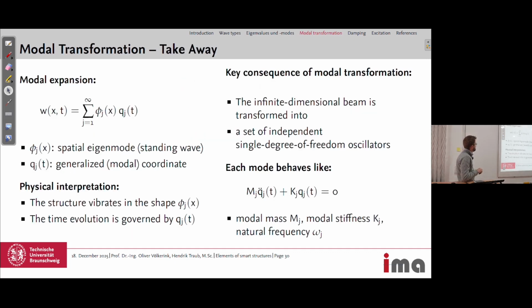So the takeaway is, if we assume this general solution with the separation ansatz, so the spatial eigenmode with its standing waves, and the generalized modal coordinate, which describes the change in time, then the structure vibrates in this shape, and the time evolution of the vibration is described with this modal coordinate.